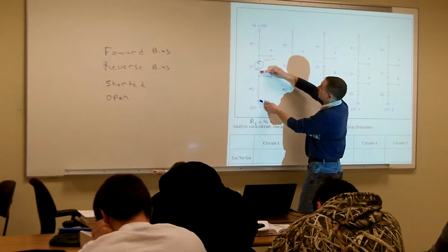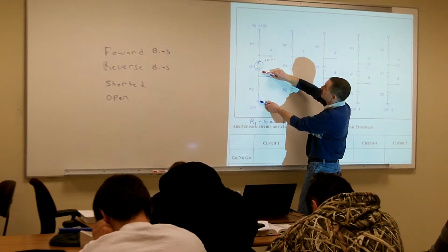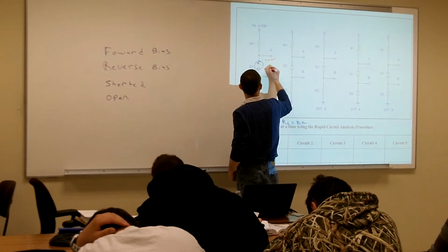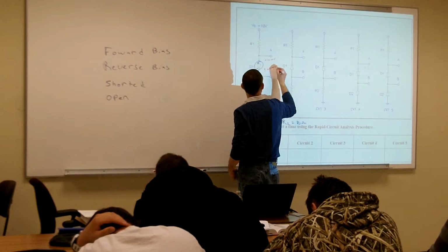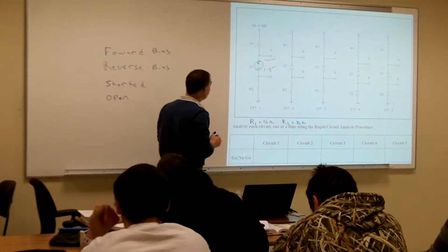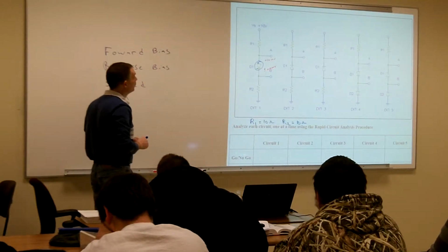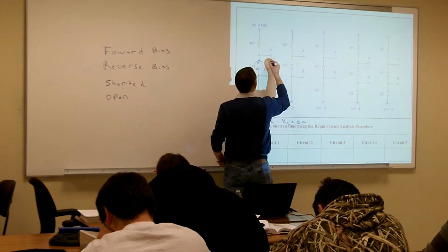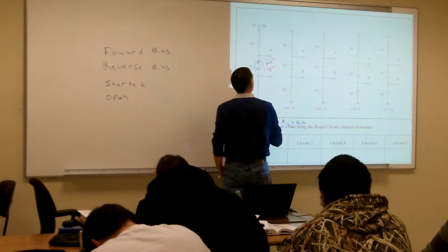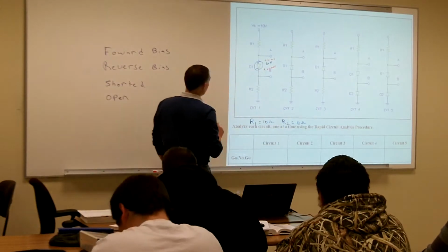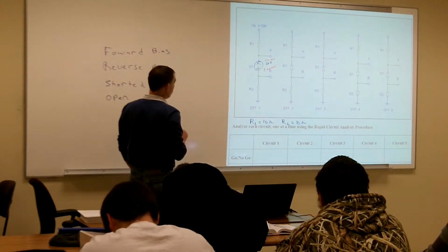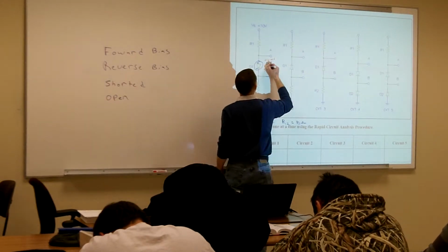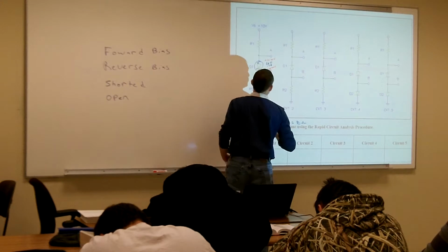And then what would I measure for voltage on the bottom side? Plus or minus 0. So those are all my soft voltages. Okay, that diode, go or no go? That's a go, and then it's going to take its voltage first. And what's the voltage across the diode going to be then? 0.7 volts.